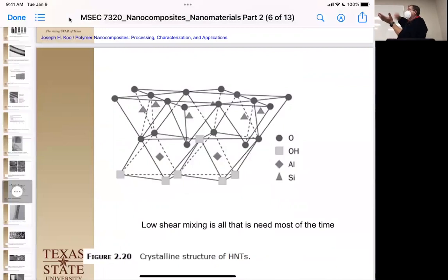And so it'll curl and even, many times, spiral. So it's technically an aluminosilicate just as the 1D stuff is, but instead of being flat plates, it rolls into spirals, and those spirals end up being two-dimensional across the diameter, but they tend to be more macroscopic across there. Now, because of this, there's less interfacial surface area between the clay and the clay on the two different nanotubes, and they're much easier to disperse.